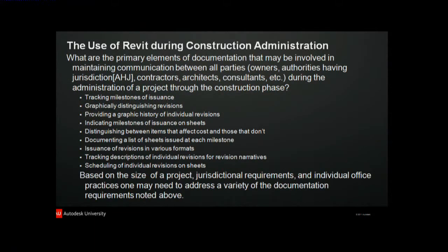So what documentation are we talking about when we're talking about documentation used in communicating between all the interested parties involved in construction administration? Tracking milestones of issuance. An example of that is that you may need a list of when documents were issued.